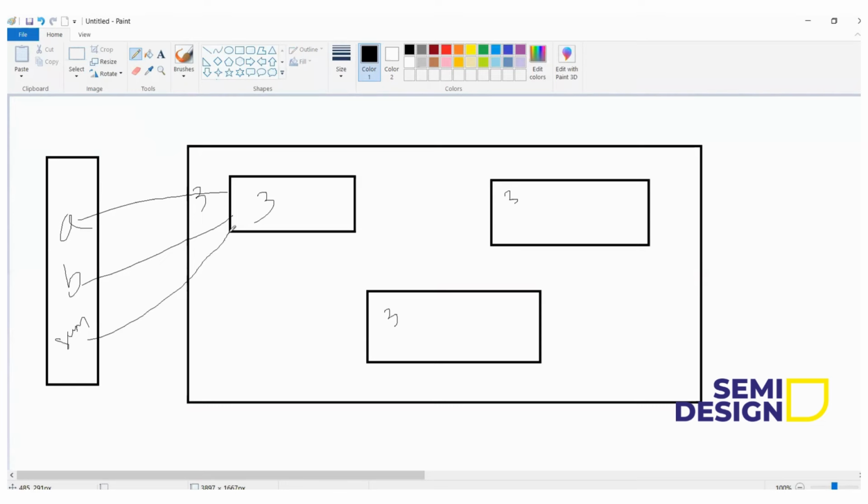So what will happen here? If I need to add some signal, I have to add it in the interface. Next, I have to do the connection. Instead of writing the signal name variable 1, variable 2, variable 3, I have to write interface dot variable 1. That means use the variable that is declared inside the interface. Okay, ma'am. So what is the advantage here? Addition and deletion of signals are easy. We don't have to retype everything everywhere in the code.